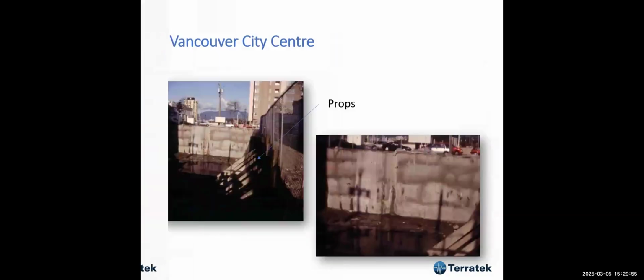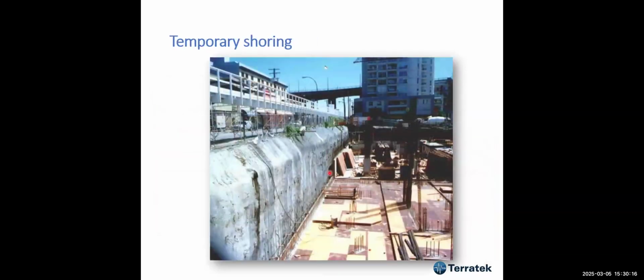It's in the city center in Vancouver. And this is an excavation for a building. Very interesting. In this area here, they could put the nails in, but in this area, they could not, for the neighbor would not allow them to put the nails in, so they had to use props like that.